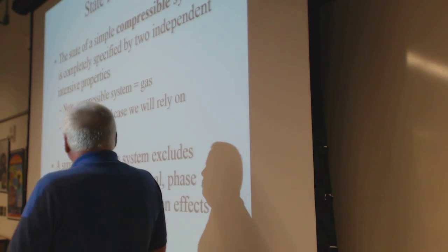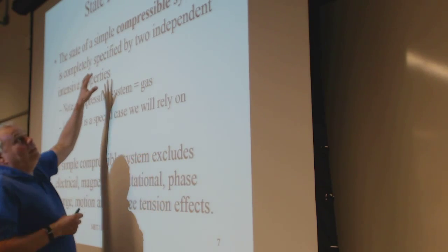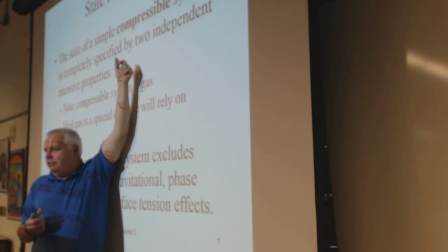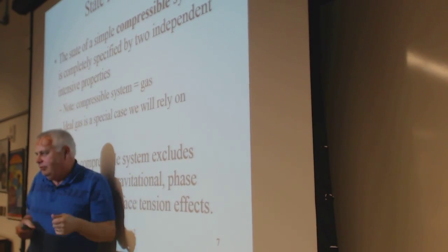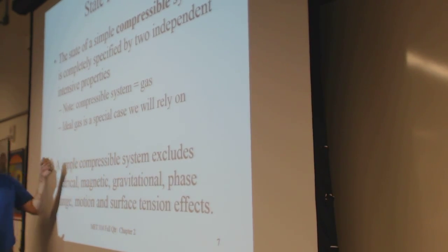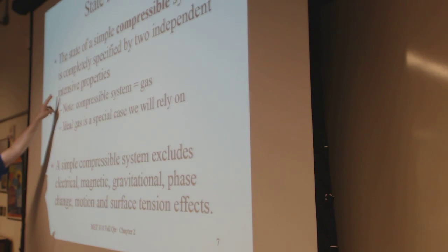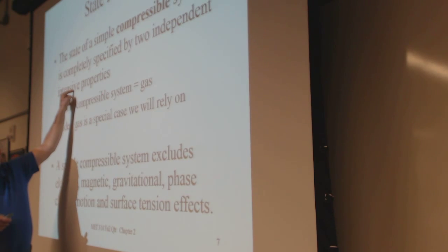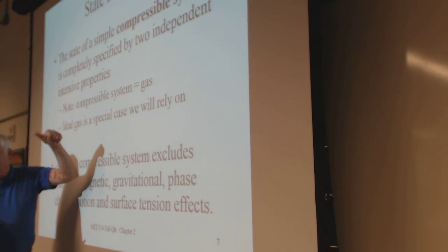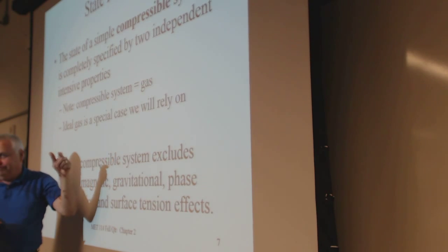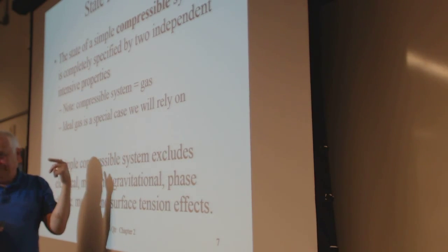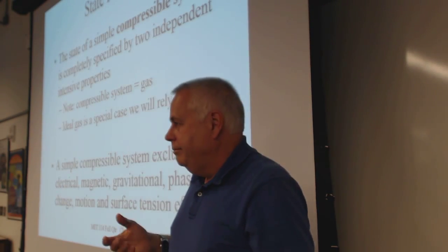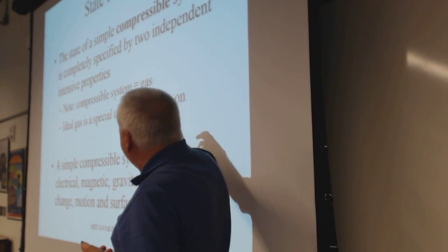So, the state of a simple compressible system. When we say compressible, we're talking gases. Liquids don't compress very well. If you know two independent intensive properties, density and temperature, or pressure and temperature, that's enough.